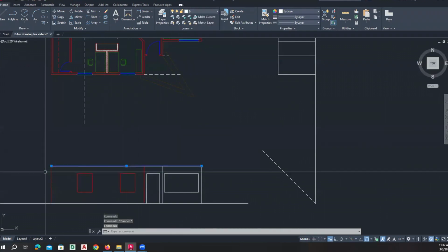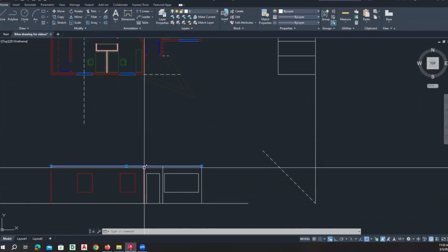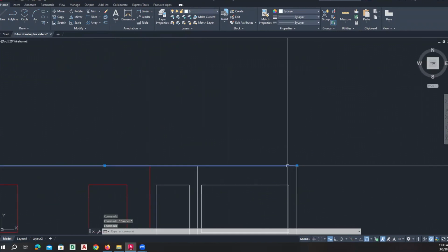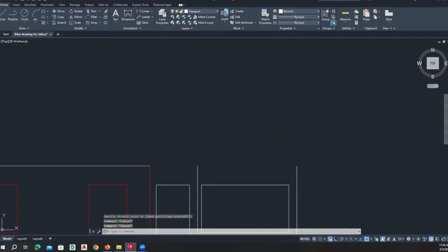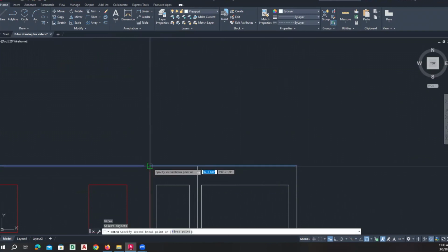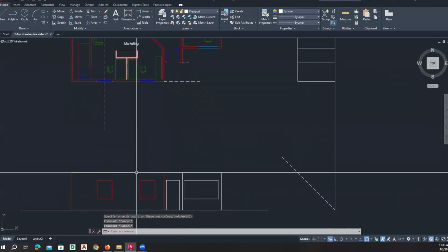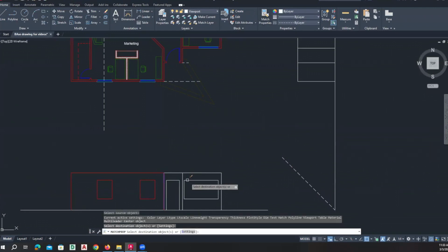This part of the roof line, certainly, but then if you notice, it jogs back here if it follows the wall, right? So that means this portion should be on a different layer. So what I could do is take this line and break it. A couple of things I could do. I could just grab this line and make it shorter, and then fill in the rest of this with 2 other line segments. The other thing I could do is use a command called break. If I select this object, I could break it there and just complete that out. And then take this and use match properties, select this and match it to that, right?